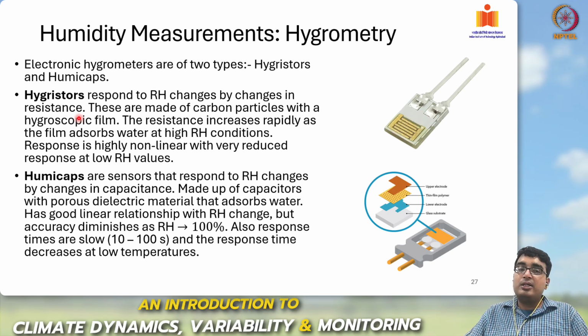So in very dry conditions, hygristors are not the best way. Whereas here, you remember, the hair hygrometer is not very good at high relative humidity cases where it's less sensitive, but is very sensitive to low relative humidity conditions. So that also needs to be taken into account.